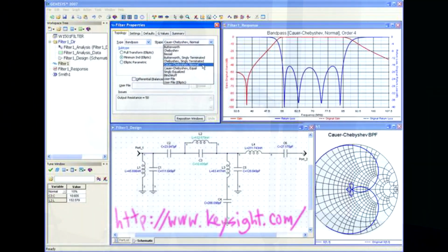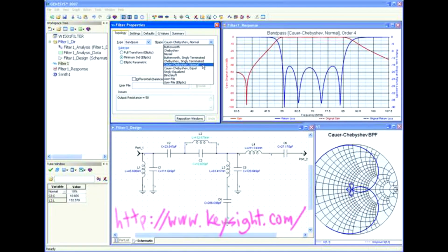Now, I mentioned that in addition to RF ICs, there are also passive components, for example, filters that you can buy in an integrated component. If you don't buy them in an integrated component, you have to build RF filters out of capacitors and inductors, and there are filter design tools that let you create this big network of capacitors and inductors, simulate it, and figure out what its frequency response is going to be.